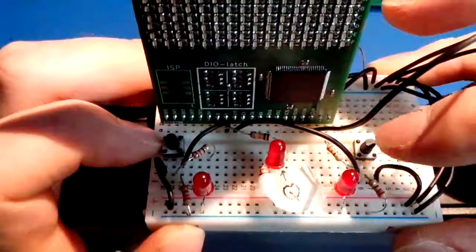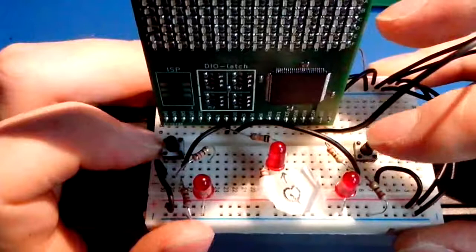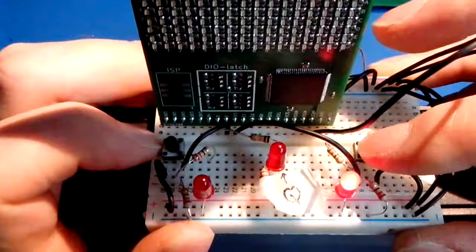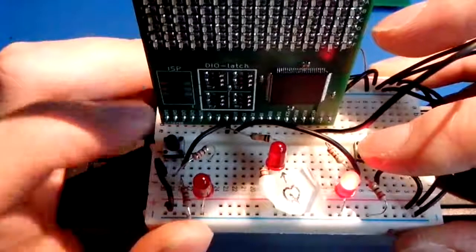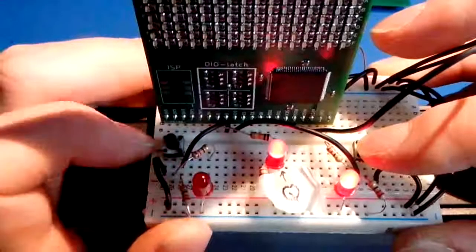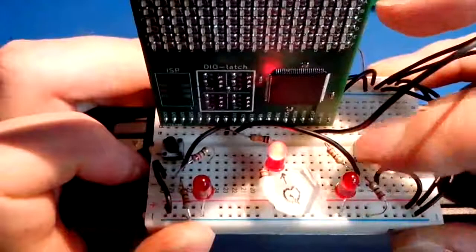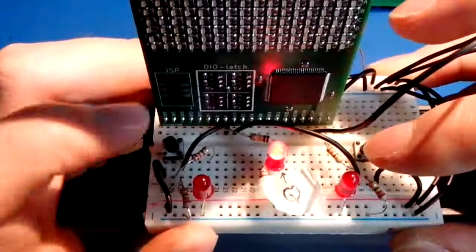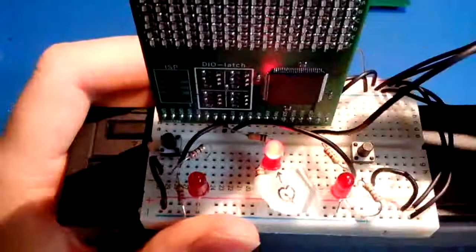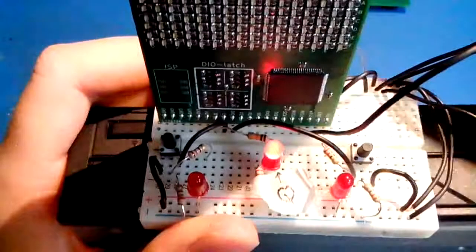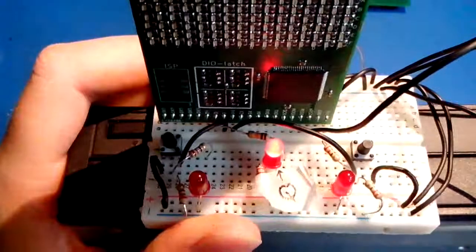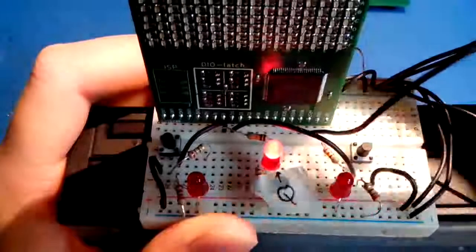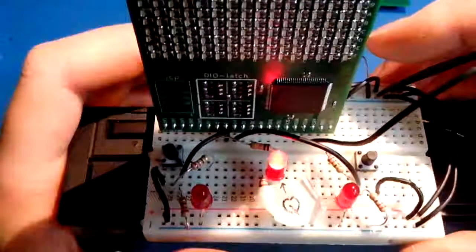Furthermore, exactly the same as with the 8-bit latch, if I apply a certain signal at the D input and I give a short pulse on the E input, like that, the D input is copied to the output and stays put, no matter what happens at the D input after that, once the enable signal is removed. Now this latch doesn't have a reset, because that doesn't make sense, because the value is latched every instruction cycle. There's no global reset necessary for this module. So that's basically how it works.